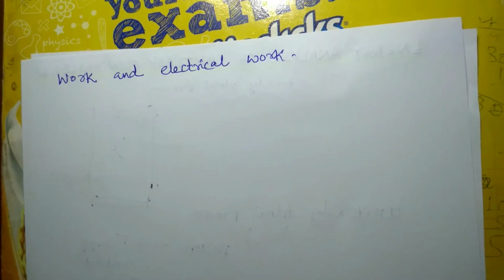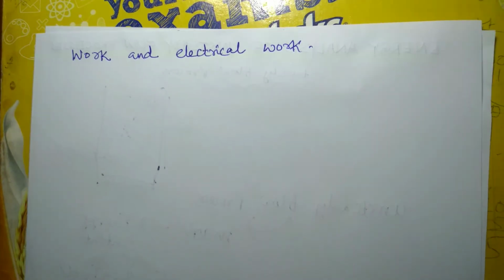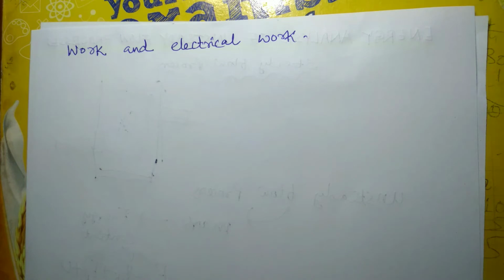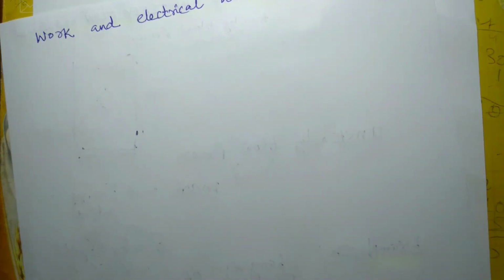In case of steady flow process, boundary work is not possible. Boundary work is totally absent. But in case of unsteady flow process, there can be boundary work along with shaft work as well as electrical work. In the steady flow energy equation that we derived, we found that W_CV only represents the shaft work or electrical work. But in this case, we can also include boundary work because the volume changes. Boundary moves here. So there may be change in size and shape.